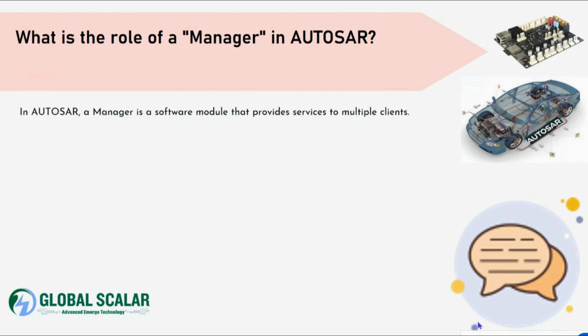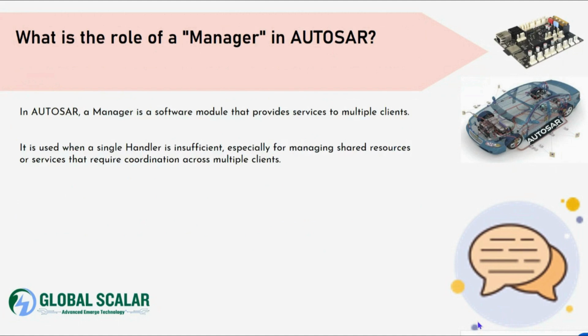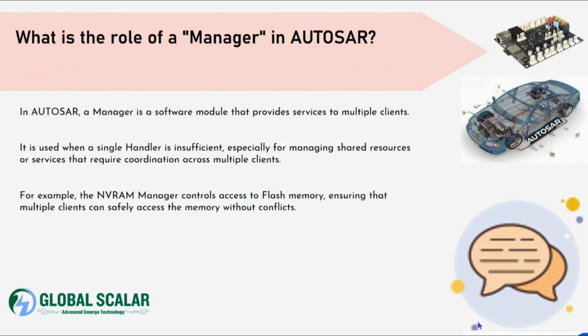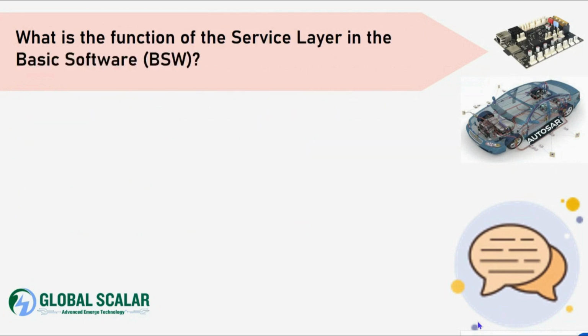What is the role of managers in AUTOSAR? In AUTOSAR, a manager is a software module that provides services to multiple clients. It is used when a single handler is insufficient, especially for managing shared resources or services that require coordination across multiple clients. For example, the NVRAM manager controls access to the flash memory, ensuring that multiple clients can safely access the memory without conflict.